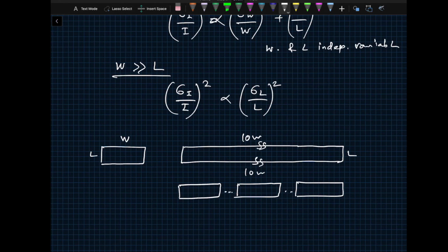Right now I'm showing only 3, but you can imagine there are 10 units like that, and each one of them is W by L. What I suggested last time was that this would be preferred because you would have the exact same statistical behavior on your W's and L's. You may get a very similar result over here because finally you can chop this transistor like this to make 10 units, and then statistically you probably get pretty much similar behavior.